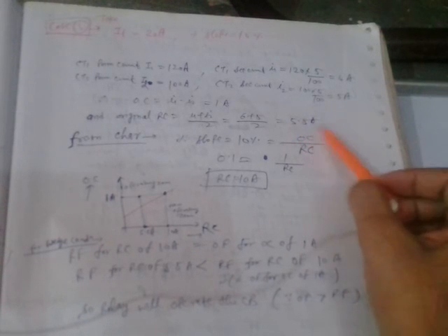But for this percentage slope of 10% and fault current of 20 ampere, the restraining force for the restraining coil current of 5.5 ampere that we calculated earlier, the original restraining current now, is less than the restraining force for the restraining coil current of 10 ampere, or the operating force for the operating coil current of 1 ampere. So the relay will definitely operate the circuit breaker. Relay will definitely operate because the operating force is more than the restraining force.